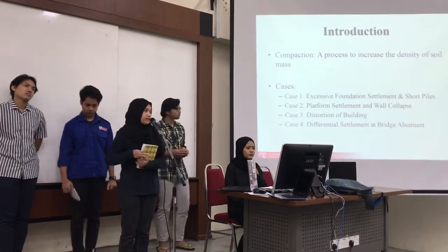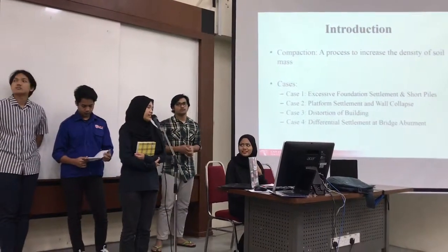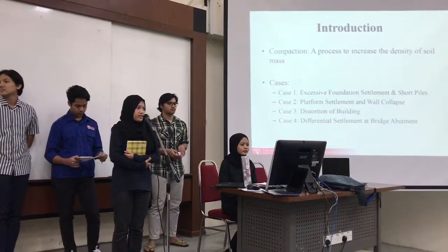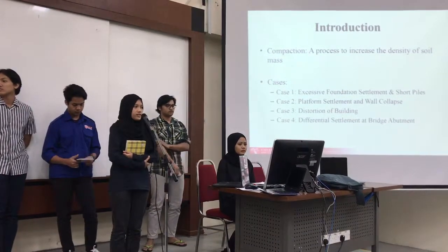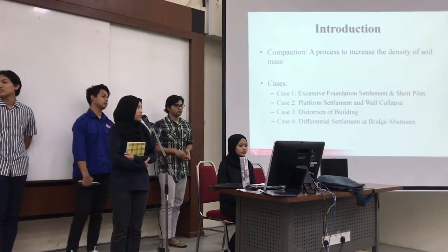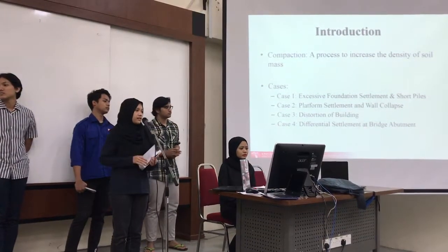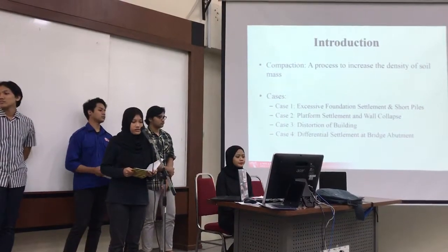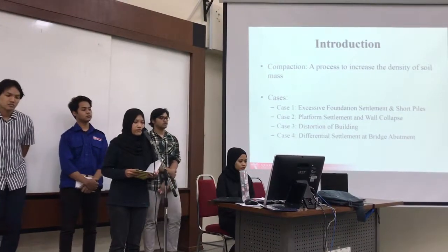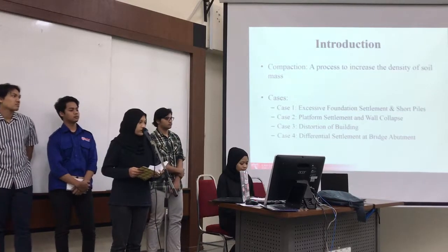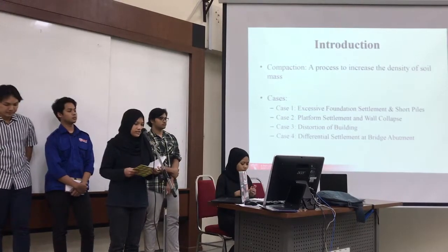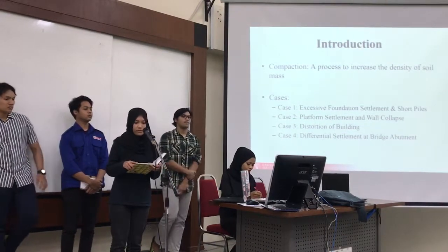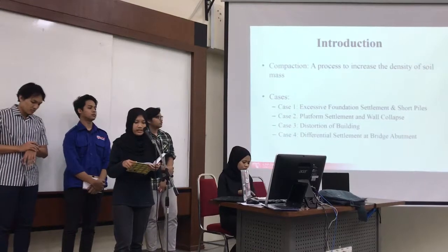In this project, I will explain a few cases which occurred in Malaysia. The first case is excessive foundation settlement and short piles. This case involved about 40 units of single-story houses and 70 units of double-story houses. The problems that occurred in this case are platform settlement and structural cracking.